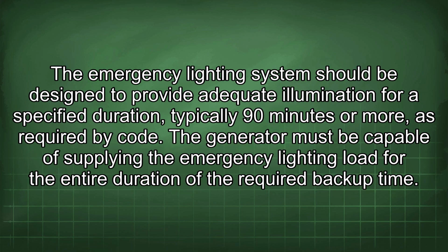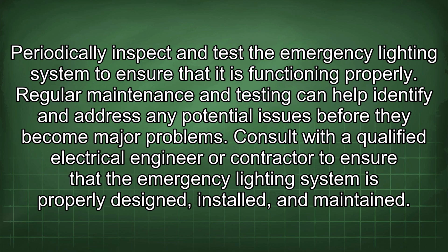The emergency lighting system should be designed to provide adequate illumination for a specified duration, typically 90 minutes or more, as required by code. The generator must be capable of supplying the emergency lighting load for the entire duration of the required backup time. Periodically inspect and test the emergency lighting system to ensure that it is functioning properly.